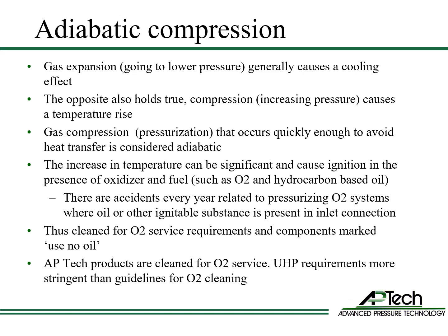There are accidents every year with residual oil present in the inlet connection when an O2 cylinder is opened. This is the purpose of the cleaned for O2 service requirements and components that are marked use no oil. All APTEC products are cleaned for oxygen service. Ultra-high purity requirements are more stringent than guidelines for oxygen cleaning.